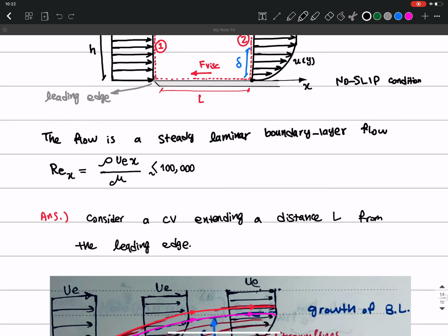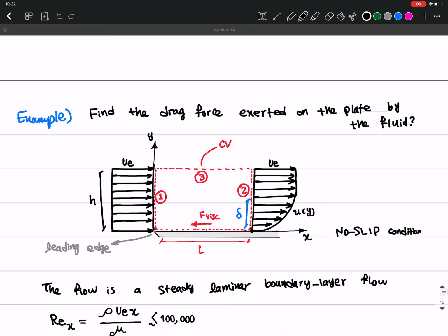So I also need to write the vertical velocity that might go out here. It could be small, smaller than the other parts, but I also need to write it down in the mass conservation, because it is also going out of the considered CV, in order to be accurate.